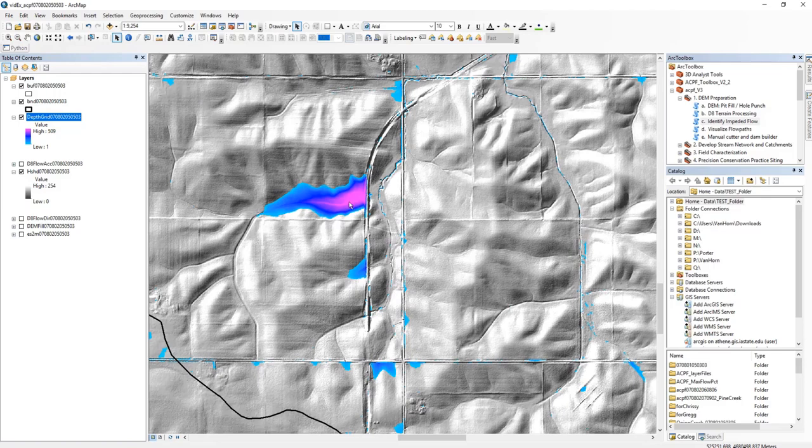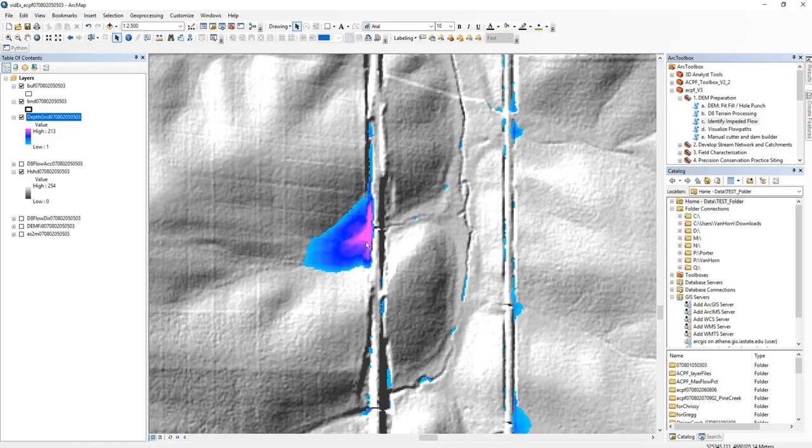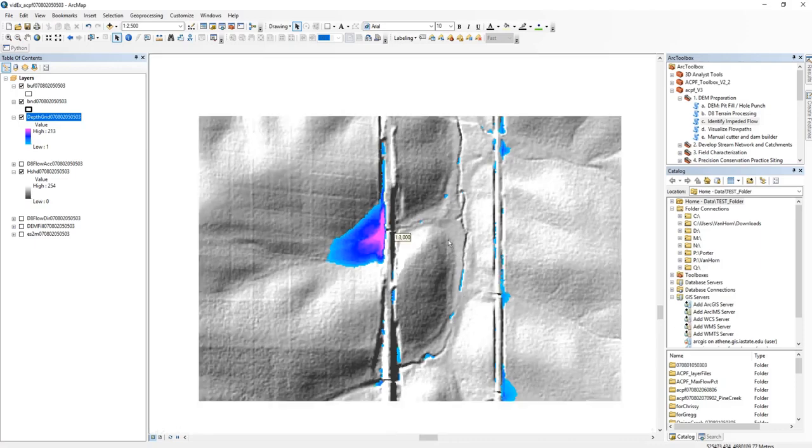And these, applied with the hillshade and aerial imagery, give a good idea of where you're going to need to be placing cuts. For example, along this one, I would do from the deepest point all the way across this roadway feature so it can continue to flow into this stream.